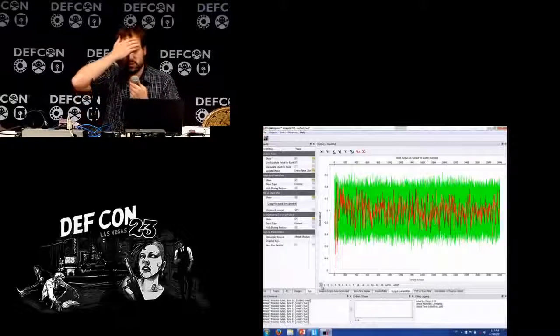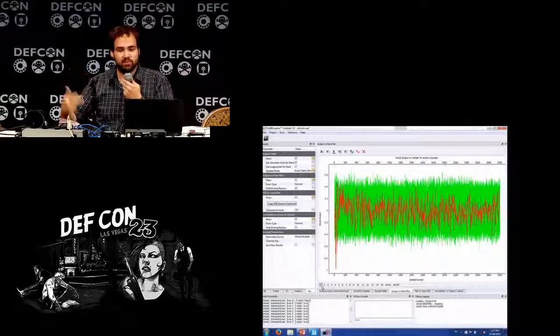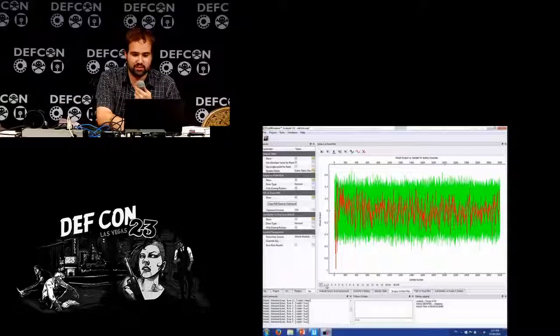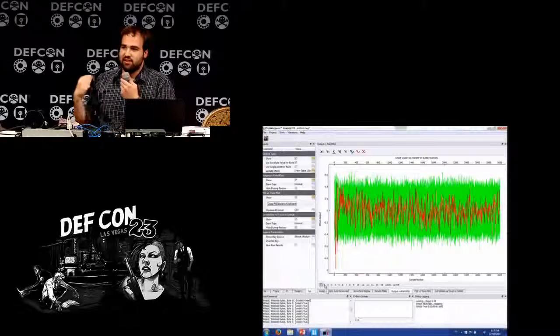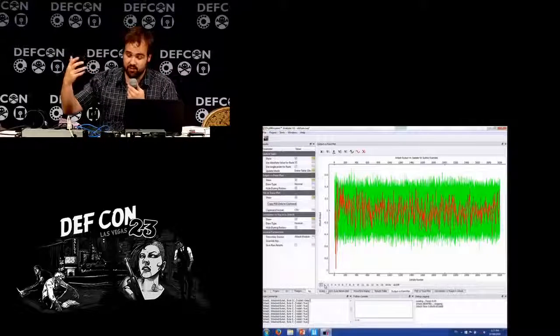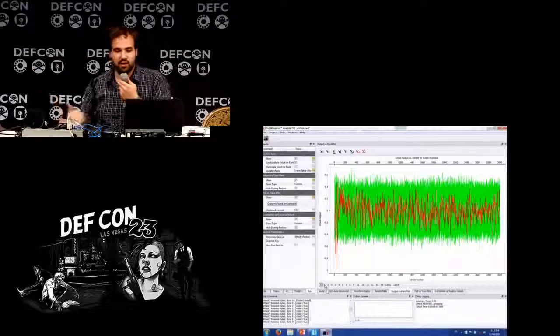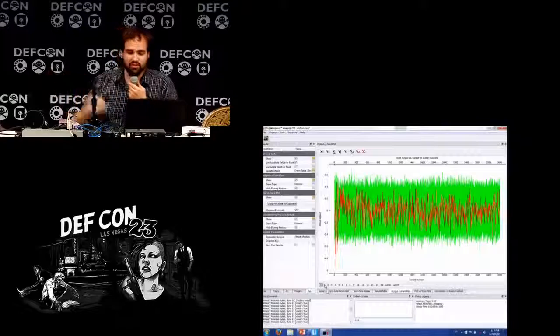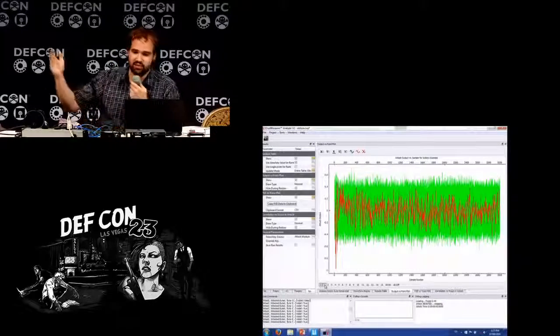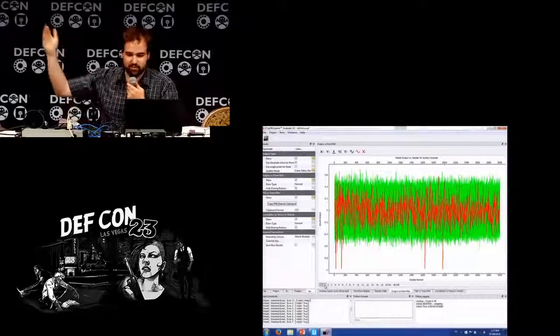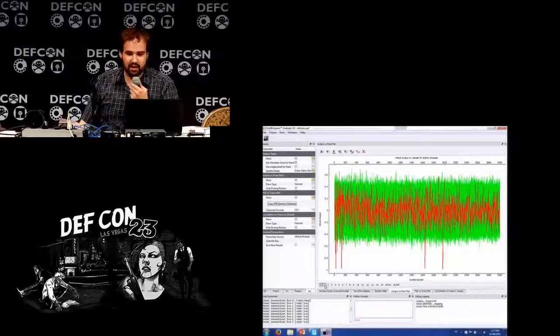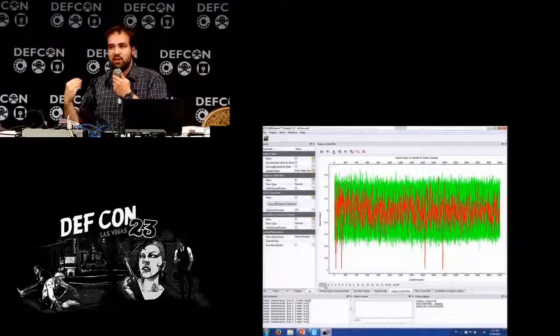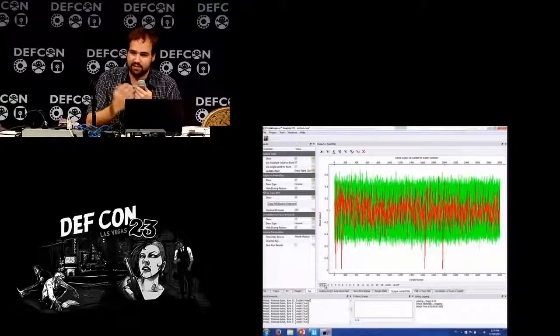And you might also ask, well, how did I know where that specific operation occurred? It actually doesn't matter because I just sent some data to the device, it encrypted it, and responded. I just took a whole section of that power consumption. And I can ask it, for example, where in time, and these are these big red spikes, was there a high correlation? Where in time did you see that data dependency?